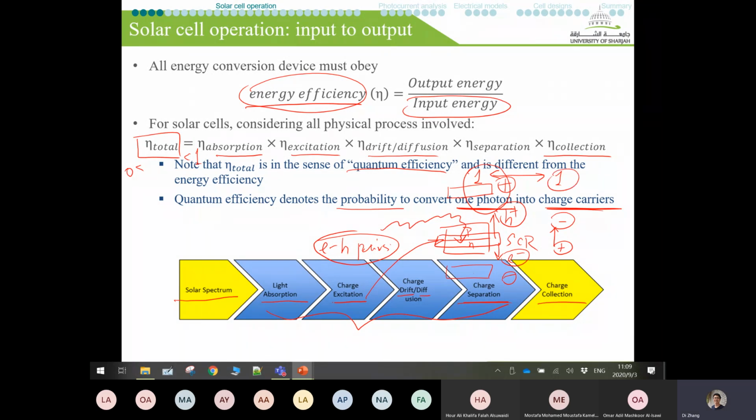And then for one charge carrier, you can calculate how much that is in terms of the current or current density, because we mentioned the current density definition last time. So you'll be able to know how much current or current density we generate from one charge carrier. The only missing information is that for energy or power, we need to know how much potential we are creating. If you also have the potential from the solar cell, then you can calculate the power or the energy, because we're just talking about the one photon case.